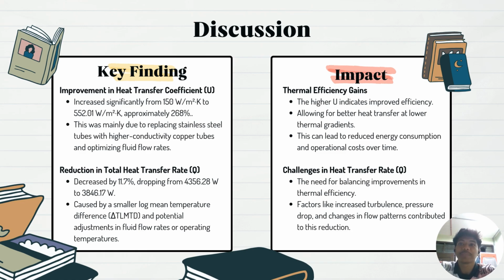And second, the total heat transfer decreased by 11.7%. It dropped from 4356 to 3846. This is caused by a smaller log mean temperature difference, which is LMTD, and also a potential adjustment in fluid flow rates or operating temperature.